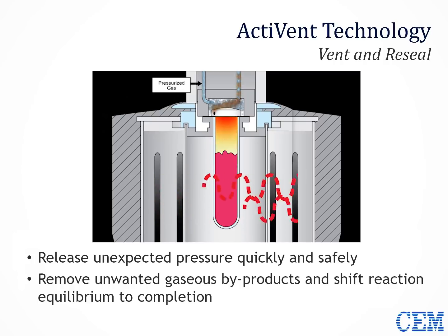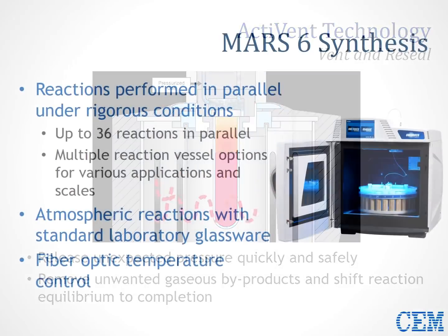So venting can occur at pre-programmed pressures while the method is running or when the safety limits of the system have been reached. So by automatically relieving the gaseous byproducts, the silicone caps and the pressure device minimize overpressurization. This significantly reduces our vessel failures and allows your reactions to reach higher temperatures. The caps offer a safe seal without the need for crimping tools.